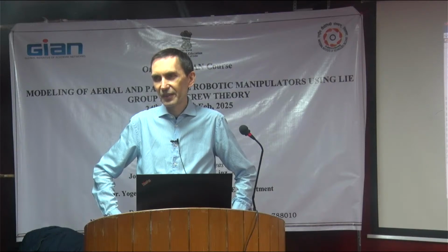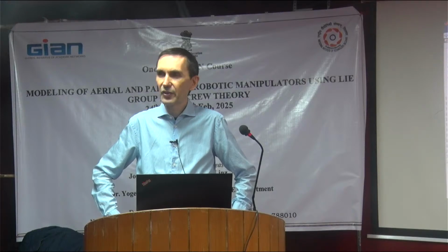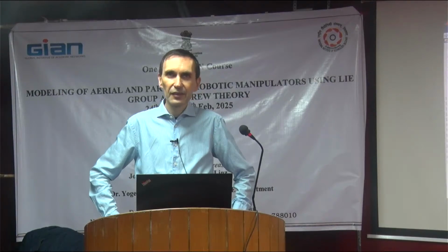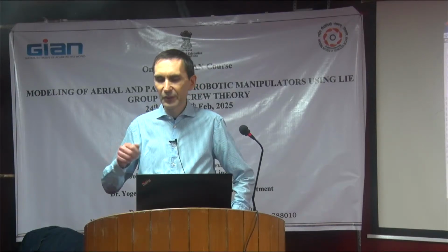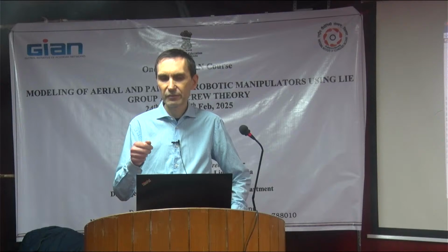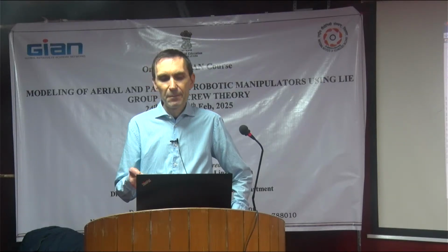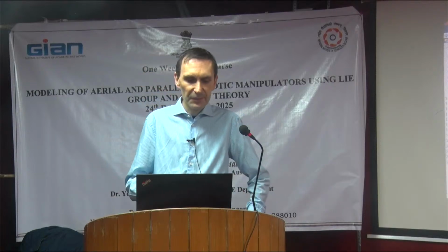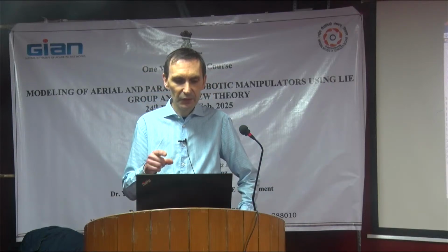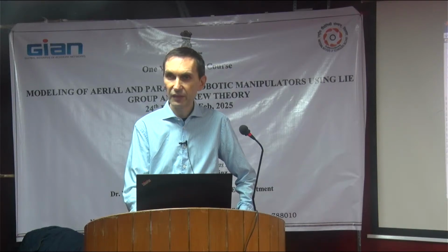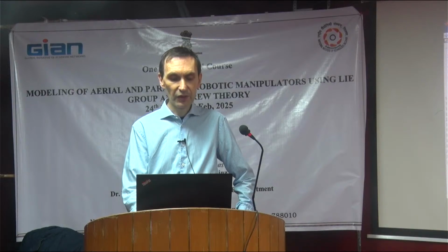Exactly. A prismatic joint has an infinite pitch. It's like saying you would need an infinite translation to get a rotation, which means you never get a rotation. In this case, the screw coordinate looks different, because then the screw coordinate is just the unit vector. Okay, good. So this is the function.